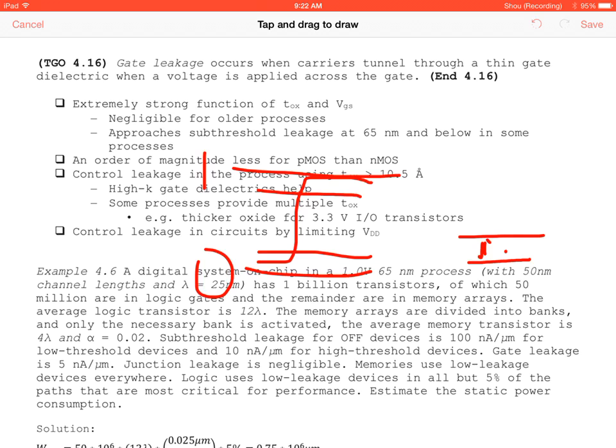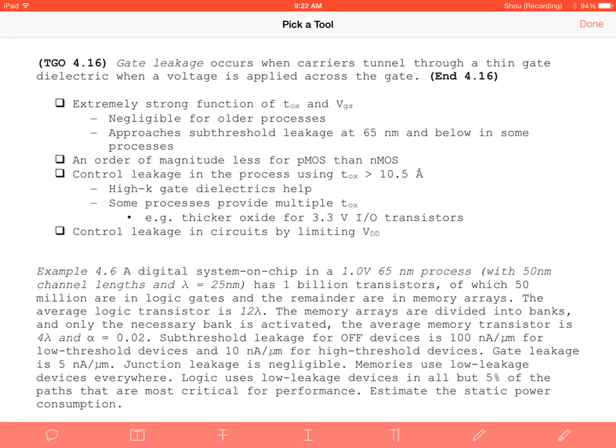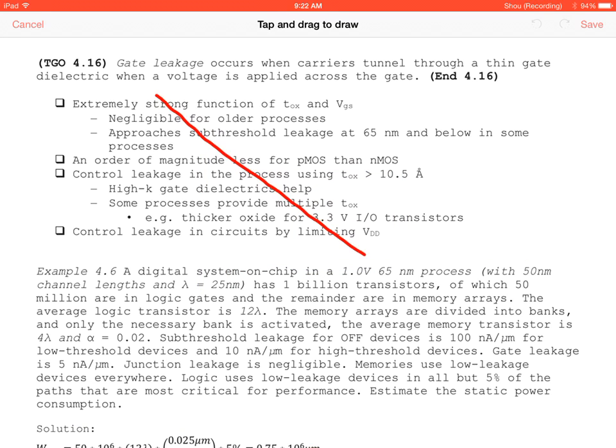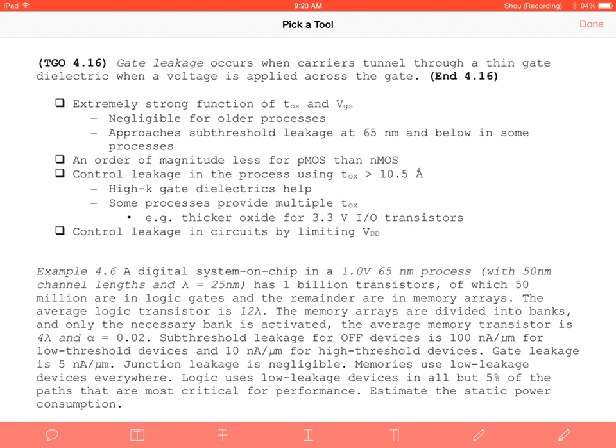So ultimately, the smaller and smaller you make VDD in the same transistor size, it becomes more and more difficult to actually differentiate those. Now, one of the benefits, as you've been starting to see, is that we are getting lower and lower. We're currently at 22 nanometer, and Intel's starting to do 14 nanometer transistors. As the size gets smaller, you typically can have a smaller supply voltage. But then we come across other issues like DIBL and gate leakage. Does anybody have any questions about that?